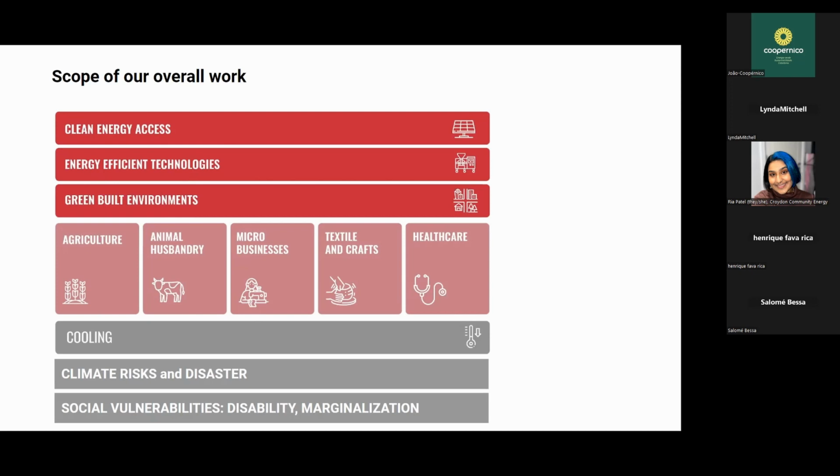So I'll give you the example of a home-based worker who is making local snacks. This person is living in a house-cum-workspace which may have a tin sheet roof, which would probably lack lighting and ventilation. So when you first start talking about an energy system, they're saying, I need to switch on the light for 12 hours in the day and run the fan for 12 hours in the day, not even counting the appliances. Whereas the reality is that if you improve the built environment, bring in natural lighting, bring in ventilation, change the materials to thermally insulating materials, you can actually then be talking about designing the clean energy system for 4 hours in the day and having natural lighting and ventilation through the rest of the day.